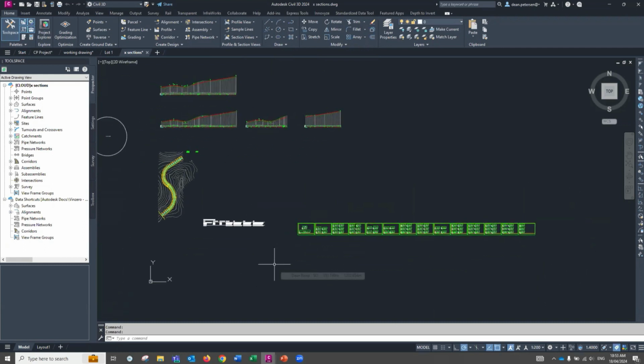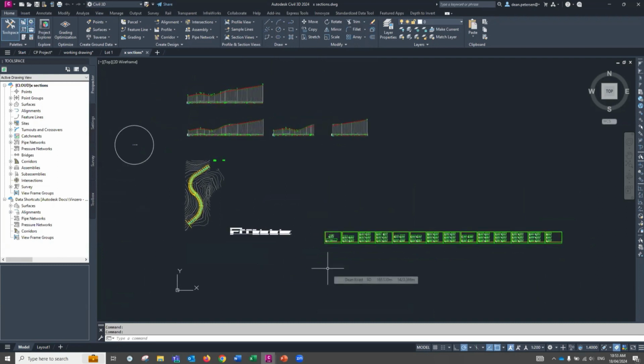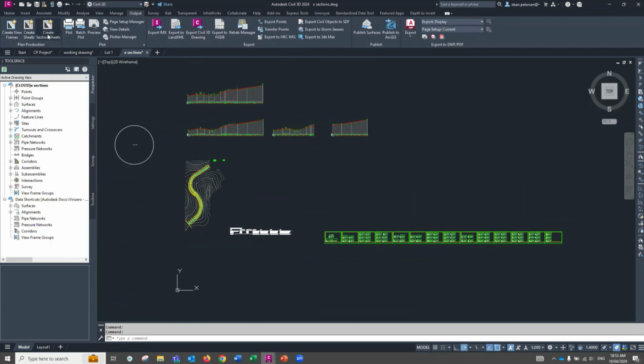Now you can create sheet sets manually in the Autodesk functionality, and you'll see that up on YouTube for various people using Autodesk, up on ACC, but I want to show you for Civil3D. So let's look at the Civil3D functionality. That is to go to the Output tab in the ribbon. Let's go create section sheets now that we've got the cross sections produced.